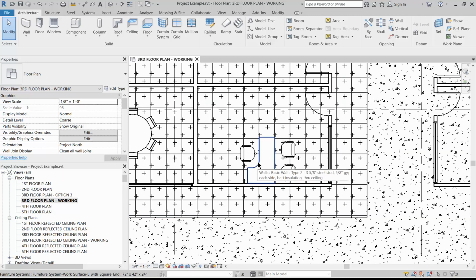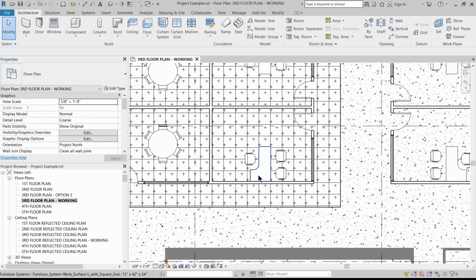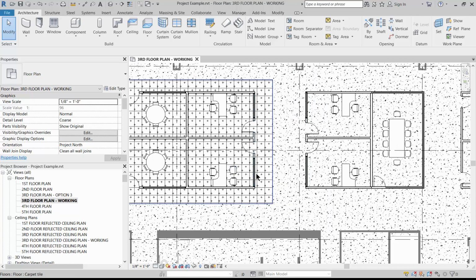If you have an issue with a pattern going through your furniture elements, and at this point in time you're probably turning off furniture for the flooring view, especially at the scales you're working in. But if the pattern is elevated, it might cover your Revit elements, which means that the three-dimensional part of the object is not showing up in plan view.